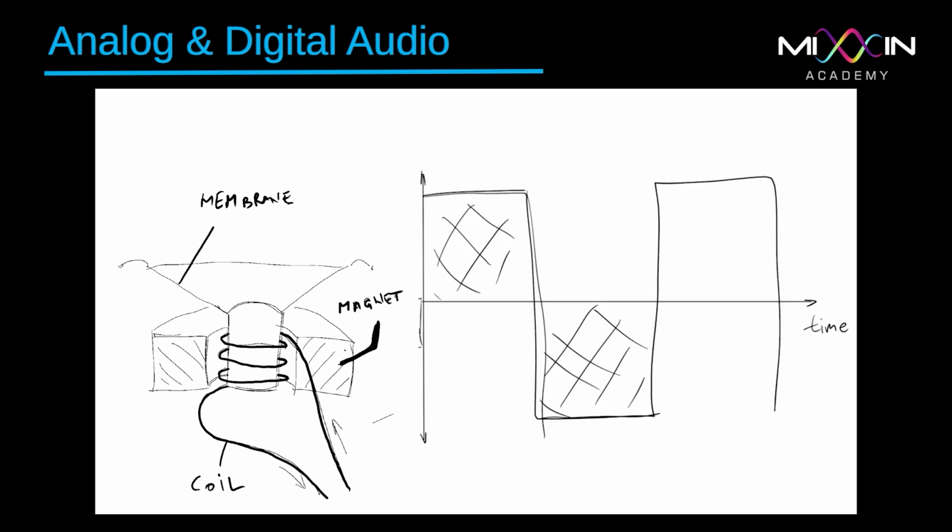We are providing sound, and in turn that sound moves the membrane, and the membrane, having the coil attached to it that's surrounded with the magnet, produces electricity that we use to have sound recorded as electricity. So a microphone is nothing else but the same version of a speaker, at least dynamic microphones, but the membrane is just much smaller so that the air pressure we provide with our voices is enough to move it sufficiently to produce enough electric energy so that we can record that as sound.